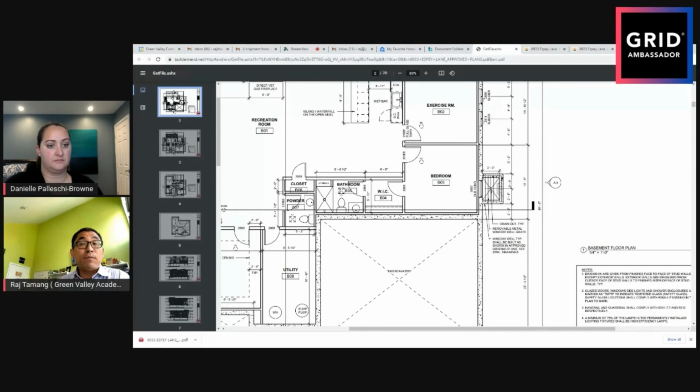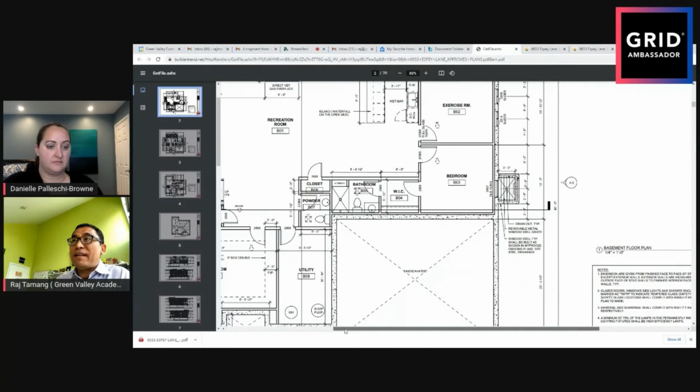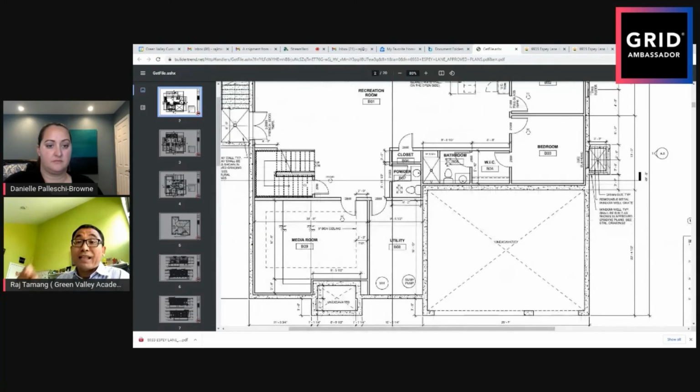to finalize before your plumber starts running the plumbing pipe, because you need to know where your sinks are going, where the fridge is. If you have a fridge nowadays, you have a water supply for the ice and the water, right? Things like that. If you have, let's say, a stove and gas, you need to know where you have to bring the gas line. Same thing with the fireplace. If you have a fireplace, you have to show exactly where the fireplace is going so that the plumber can run the gas, if it's a gas fireplace, or electricity, if that makes sense.